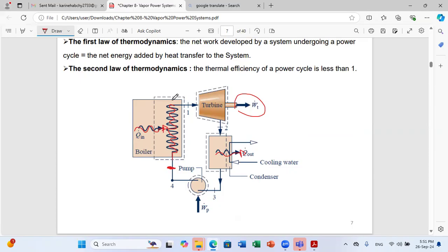In the boiler, in general, you have constant P, so you have a high pressure level in the boiler. But what will happen is that your temperature will increase from a certain low level to a high level. Sometimes the increase will not be very high because mainly you have change in phase, evaporation. But once you have completed the change in phase, you can reach higher and higher temperatures. So in general, in this system, we have increase in temperature at constant pressure, and we have change in phase.